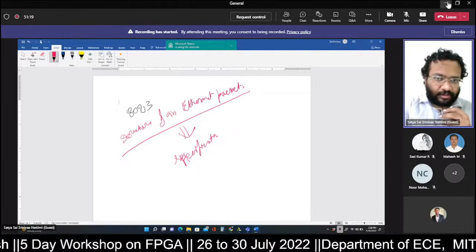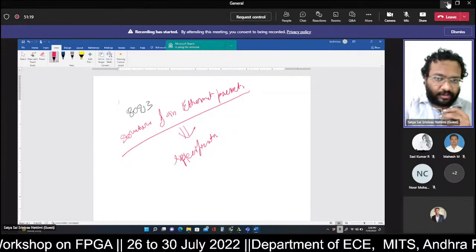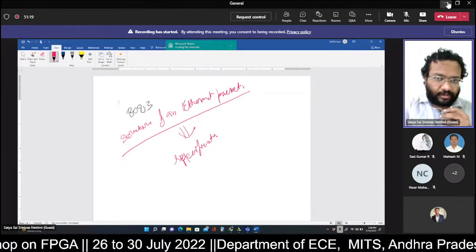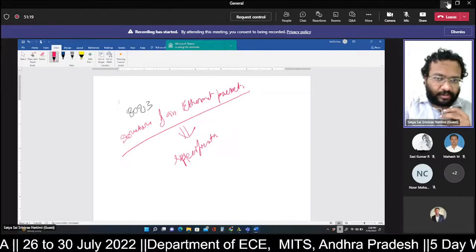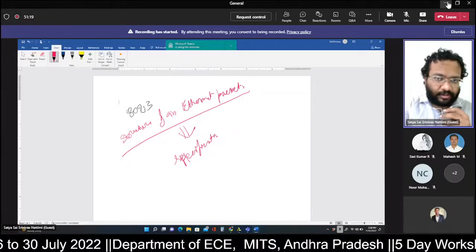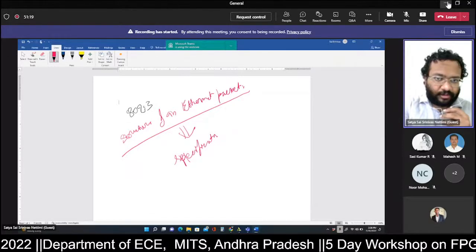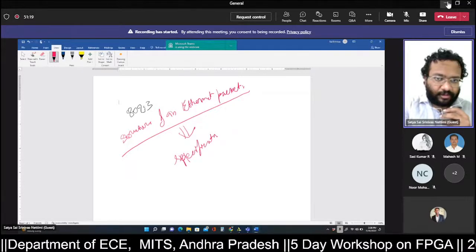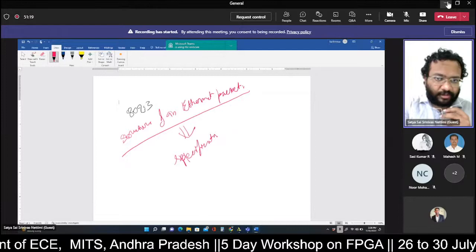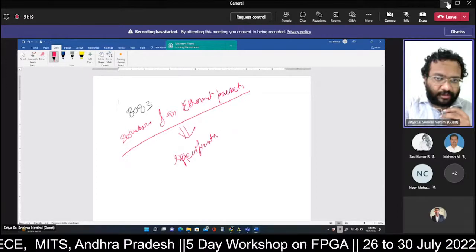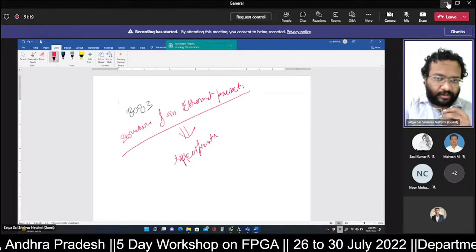Next, similarly, we will define the template for combinational next state logic. Again, we are using the behavioral level of abstraction, so we have to use procedural statements. If we are using procedural statements, we have to use always. And for the combinational next state logic, the sensitivity list is empty, since it is not sensitive to the clock. Output logic we will see whenever we are driving any outputs.